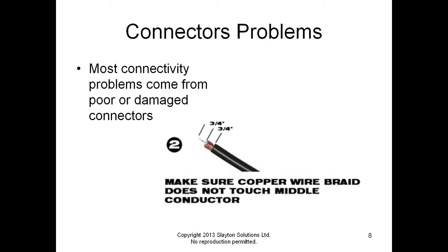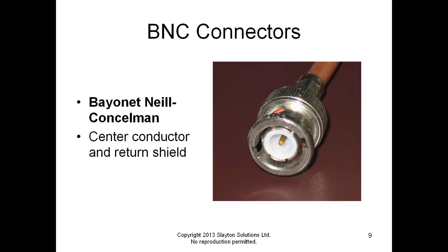This is critical with coax cables because with coax, that center conductor, because there's electricity going through it, is going to oxidize over time. It's going to get a coating on it. We want to cut off that old connector and get to fresh copper. That's where we want to put on our new connector. Now the BNC connector actually stands for Bayonet Neill-Concelman. Hey, who knew? Well, now we know.